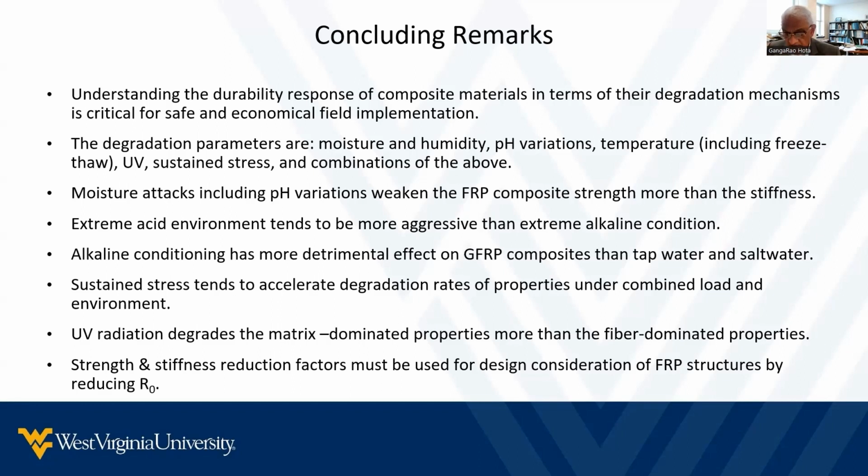Extreme acid environments tend to be more aggressive than extreme alkaline conditions. That is because the resin gets more affected than the fiber under acidic conditions. Alkaline conditions, however, are more detrimental for glass fiber composites than the tap water or salt water.